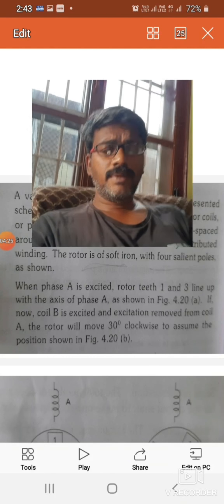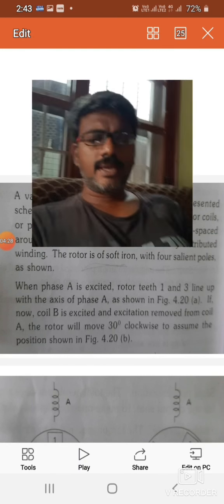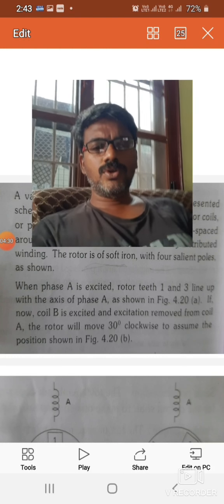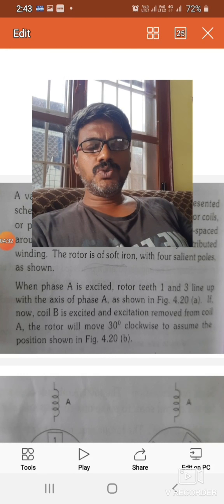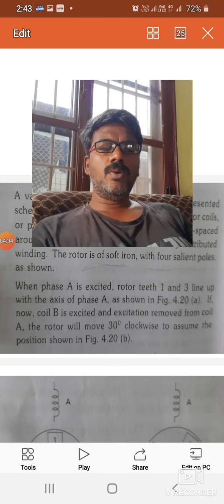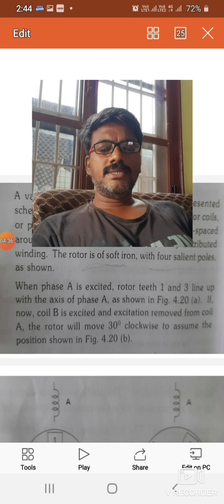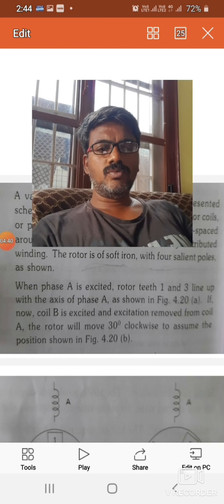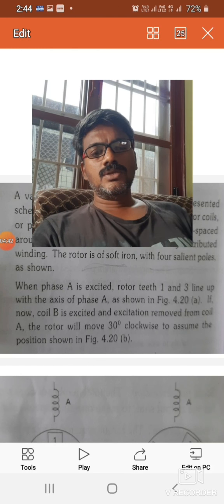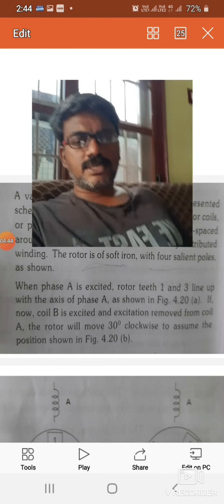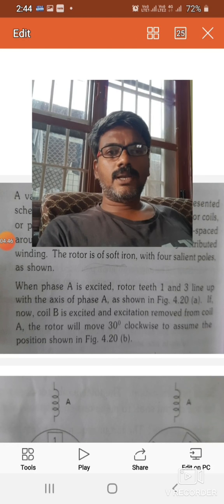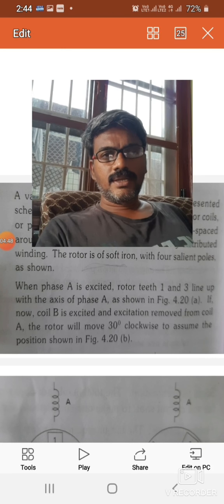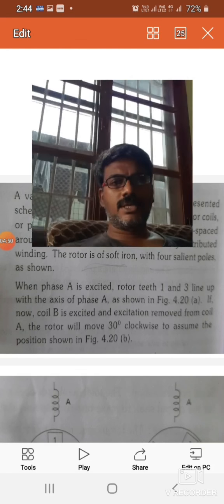So once again I will repeat: what is a stepper motor? A stepper motor is an electromotive device designed to convert a series of input power pulses, that is digital, into discrete angular movements, that is mechanical, one for each power pulse.